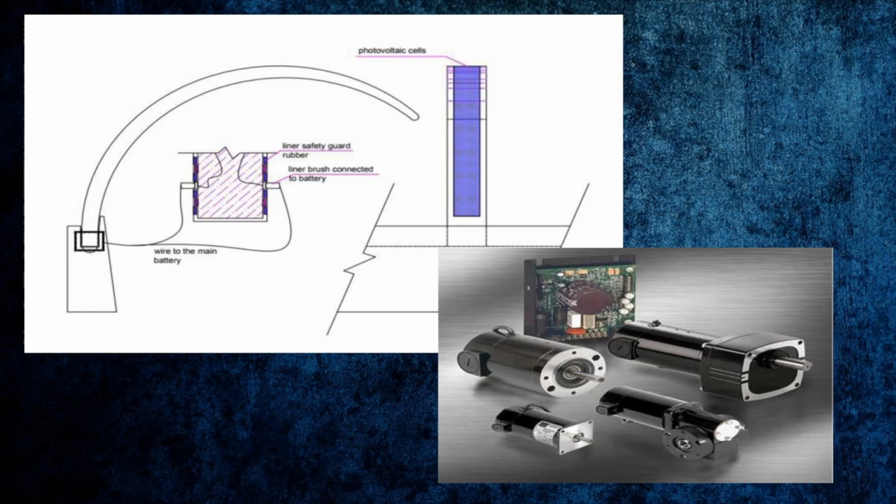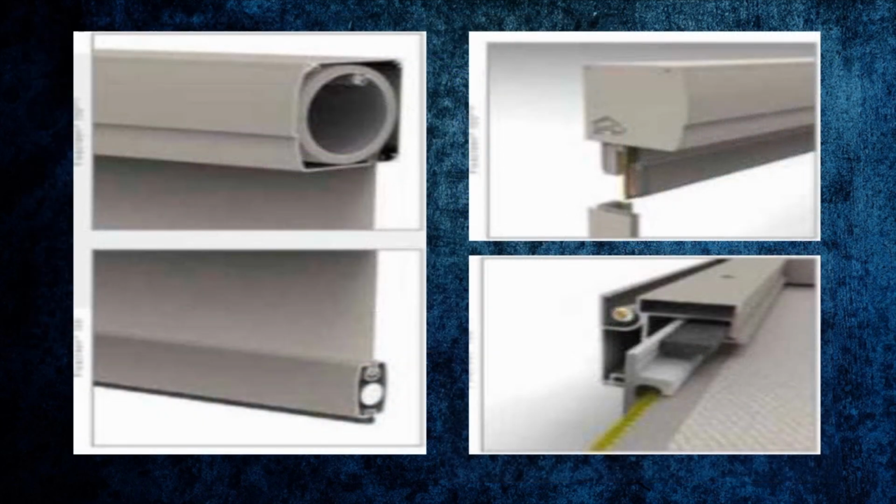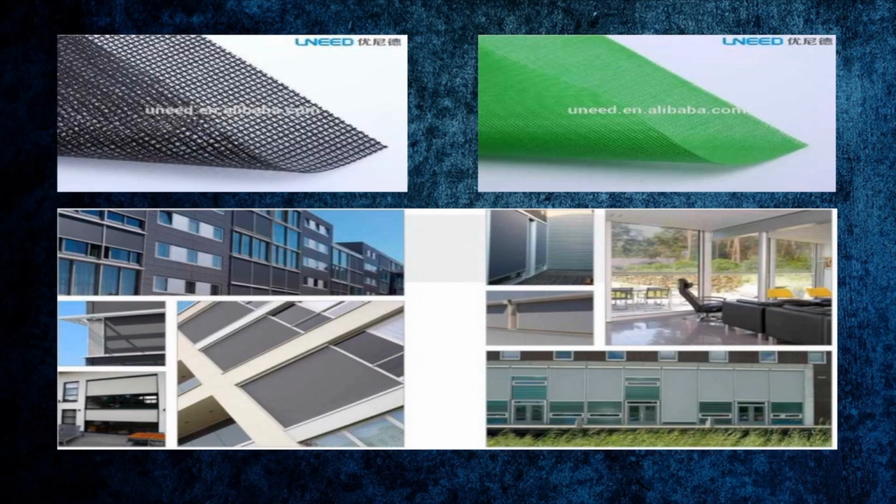Each two ribs are connected with 5 fabric strips. Each strip is connected to a motorized roller installed inside the rib. The roller motors are charged directly by the photovoltaic cells. The fabric is a PVC coated polyester mesh with a weight of 130 grams to 350 grams per square meter and thickness between 1.2 mm to 2.5 mm. It is flexible, lightweight, weather resistant, waterproof, and provides 38% transparency.